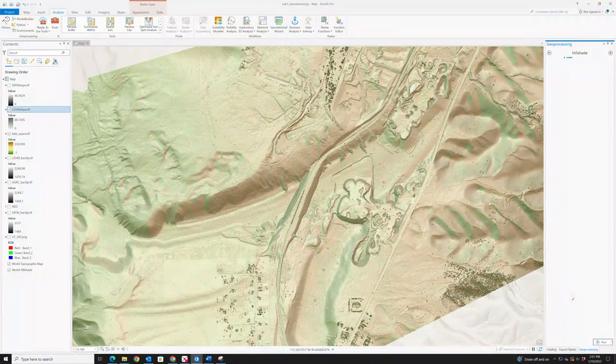So yeah, we just click on the hillshade, and then whatever raster we wanted to make a hillshade model from, we would choose it. And it's important whenever you're making these derivative surface products that you choose the correct DEM to make the surface product from. So in the case of SRTM is going to be quick. I can make the hillshade from that.